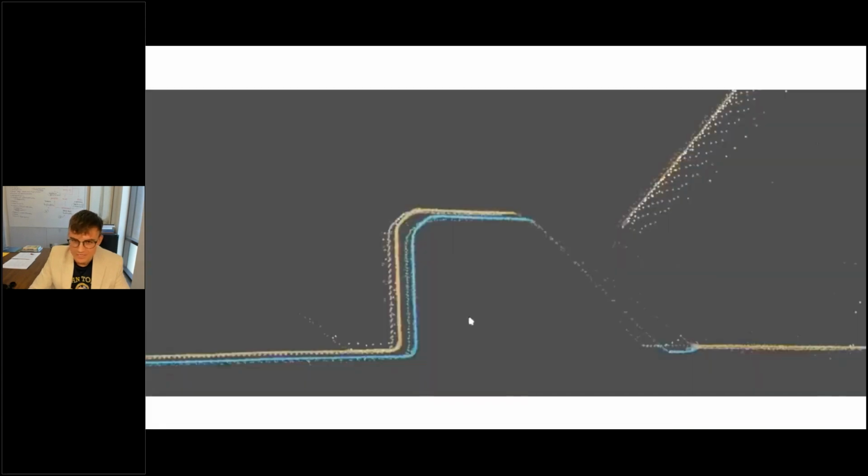Checking quality of registration. So thin slices of point clouds can reveal misalignments. Slice horizontally, slice vertically, check columns, windows, doors, piping. Look for these kinds of misalignments. And then once you're finished, get a fresh pair of eyes to QC.